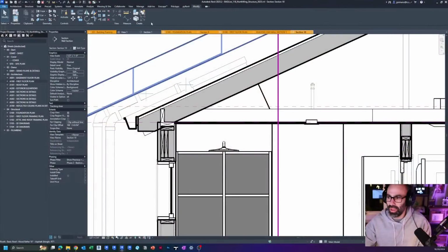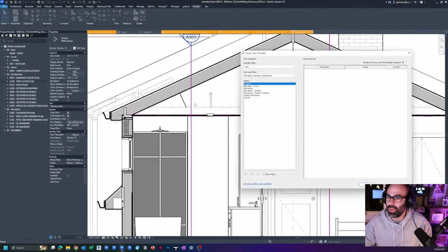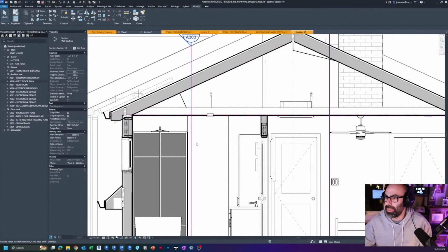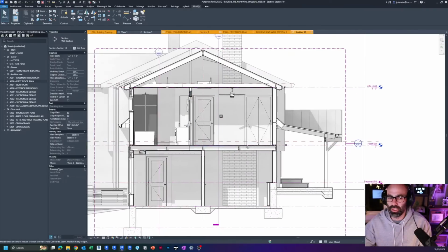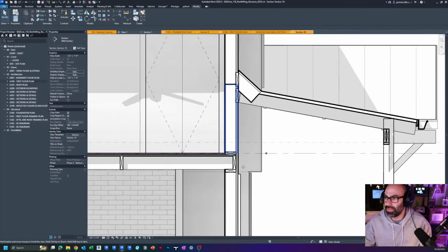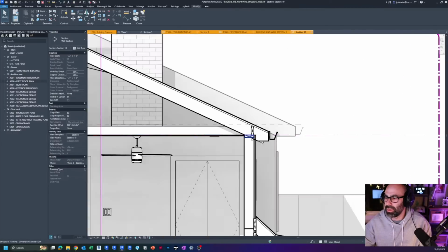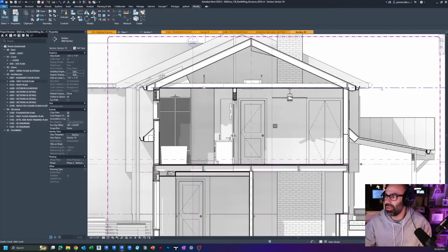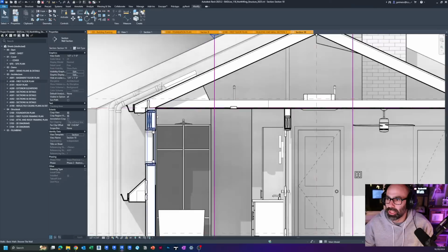And all you're doing is basically filling in the information. And actually, I'll show you real quickly, if I hit the section template, you know, how quickly this thing turns just like that. Just by hitting it with one section template, you'll notice I didn't draw a single detail on this. This is all three-dimensional items. And honestly, you can probably get away with this as is, as a building section ready to go for this type of work, right? And so that's the whole point, right?